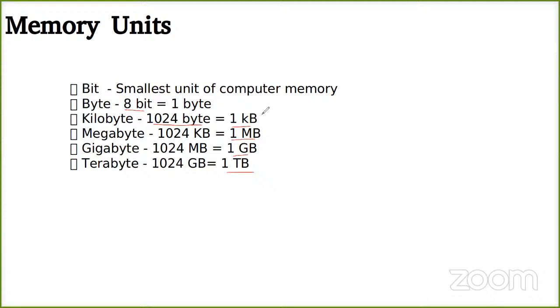Okay, our main domain is to remain inside these two things. So when we are talking of embedded, we are only concerned about bytes, kilobytes, and megabytes. Okay, megabytes is also rare. Fine. So when I talk of embedded systems, you basically have only these two to take care of. Your memory is going to be either in terms of bytes or kilobytes. For example, if you have an Arduino, it has 32 kilobytes of flash memory, and I think it has 2 kilobytes of something called SRAM, right?